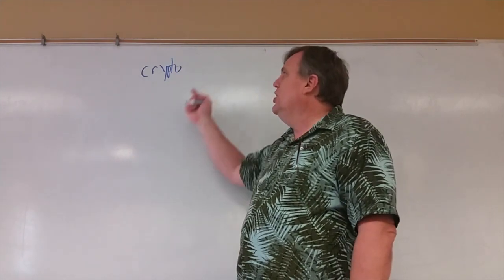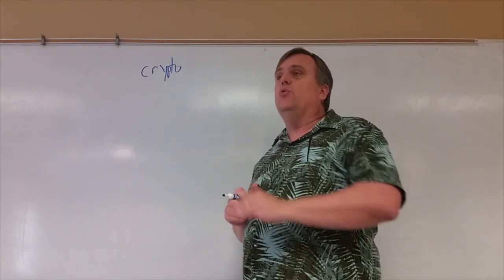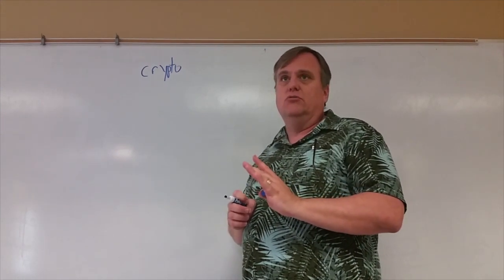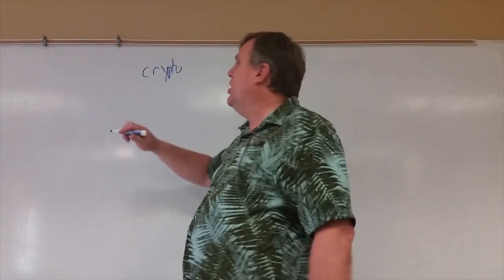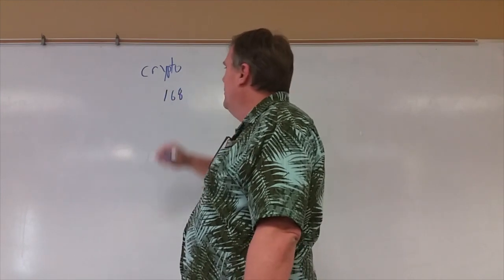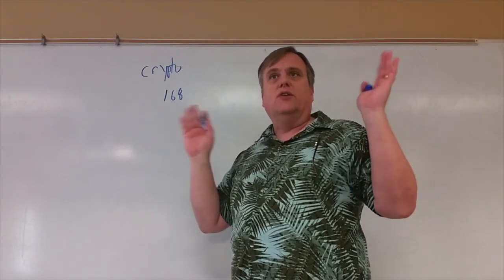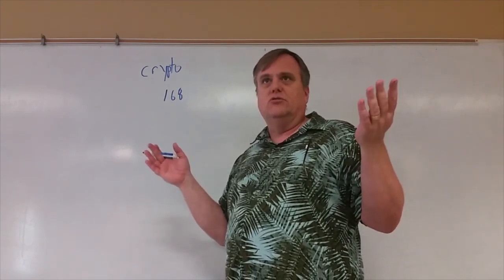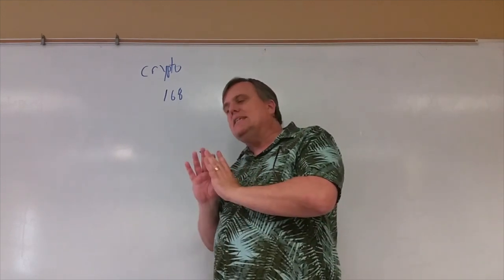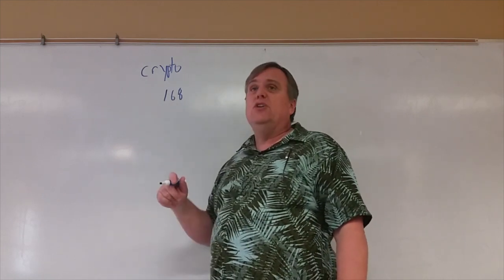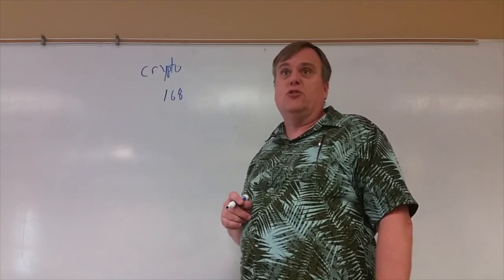If in any way you don't get a true random sequence, and you use any of these pseudo-random ones, you will get a complete garbage result. For instance, today I'm going to give you a very short piece of code for a 168-bit generator that will generate pseudo-random sequences, linear feedback shift register stuff, LFSR, that won't repeat again until 2 to the 168th cycles.